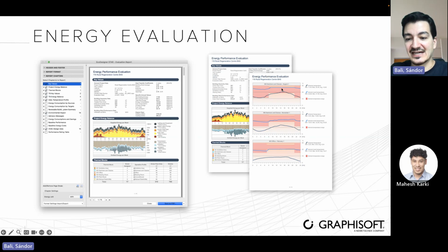There is also another page which is really nice. If we go down, break it down to thermal block, we can go to any specific date. So you can see that in the seminars and classes thermal block on 1st of August, 1st of November, and 1st of February, we can see what is the internal requirement, what is going to be the internal temperature that we achieve, and what is the external temperature out there. So it's going to be very interesting. For example, here you can see that there is a very, very short period where we cannot reach right away the internal requirement. So here we have so-called unmet load hours, but it's just 1 hour, so maybe we are okay to deal with this, or maybe we should start heating an hour earlier, right? Anyways, it's not critical.